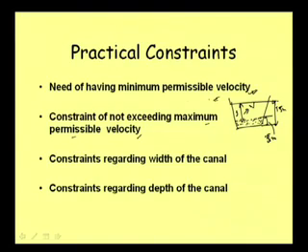And so far as minimum velocity is concerned, it is generally found to be 0.6 meter to 0.9 meter per second, and on average generally 0.7 meter per second can be considered as the minimum velocity. But maximum velocity we can go to, say, 4 meter, 5 meter, depending on the type of bank lining, but this is one consideration that we need to make.